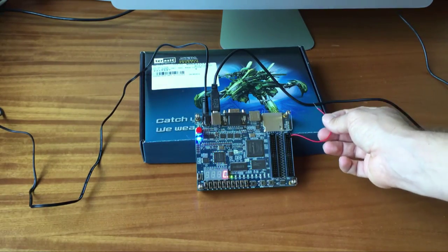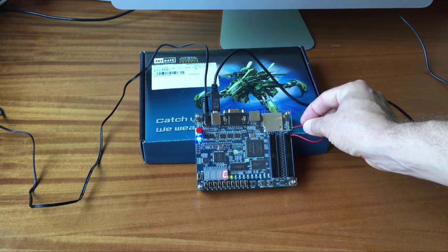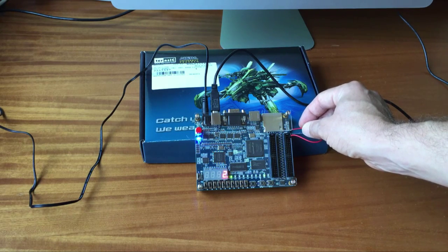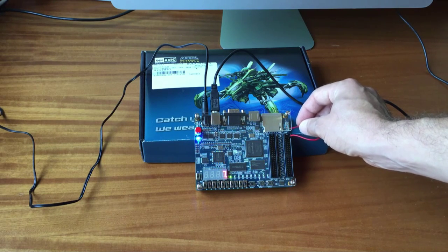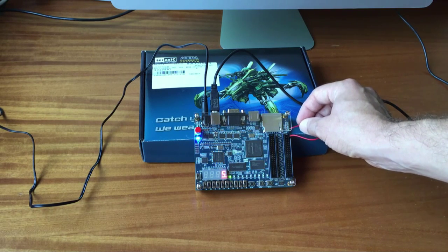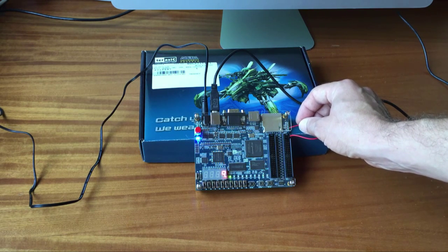Now let's try with the external switch. As you can see, when I touch the ground, the counter counts more than +1 because there is a bouncing, as you can see on the LED blinking, that provides more than one